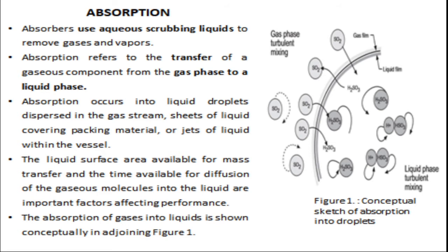Here, the liquid surface area available for mass transfer and the time available for diffusion of the gaseous molecules are of prime importance, because the contact time as well as the amount of transfer taking place will decide the efficiency of the methodology.